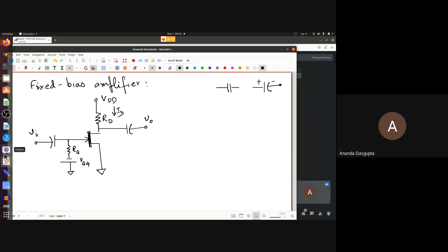But when you are taking one source, what do you do with the others? The answer is, when you're considering one source, all the other sources, not the control sources, but all the other fixed sources should be replaced by their internal impedance.